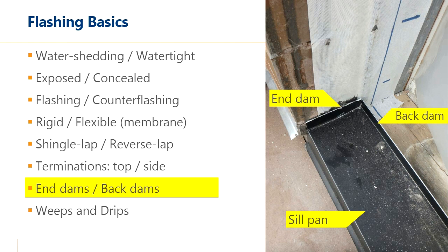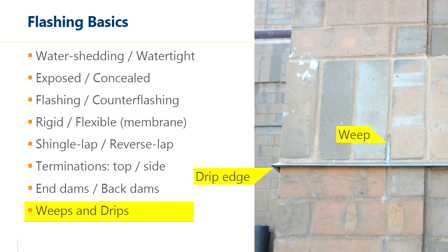That leaves the front end of this open for the most part, or if it is sealed, we need to leave intentional openings for the water to get out. And that's where weeps come in. In this case, this is a masonry weep using a corrugated plastic component. If you look closely, that weep is sitting all the way down on the metal flashing. You really want to make sure those get all the way down that you can, because any elevation that it has is additional elevation that water has to build up on the inside before it can get out.